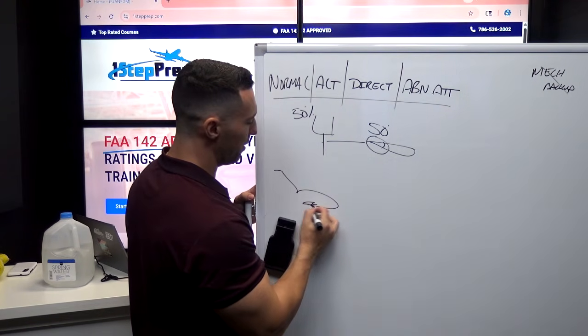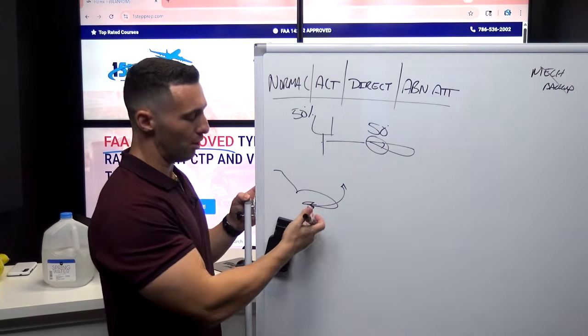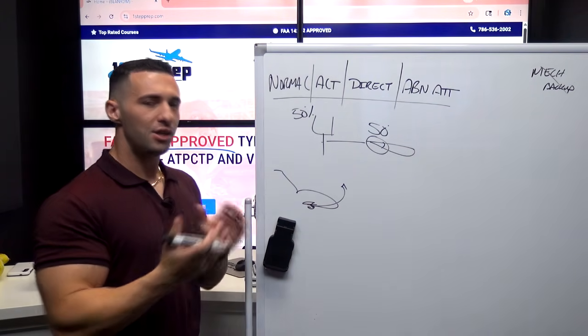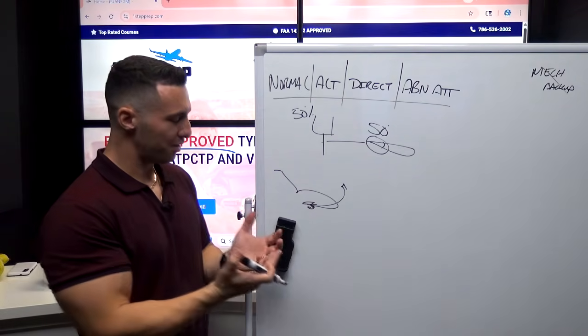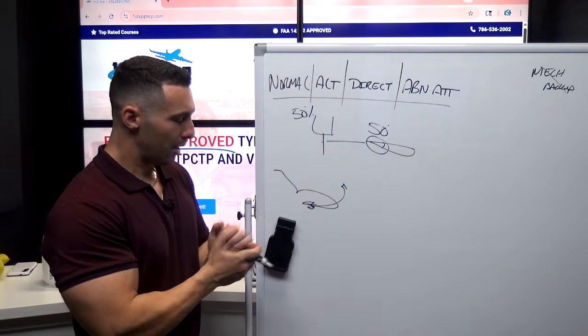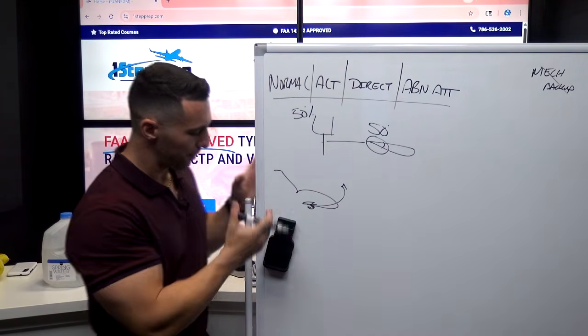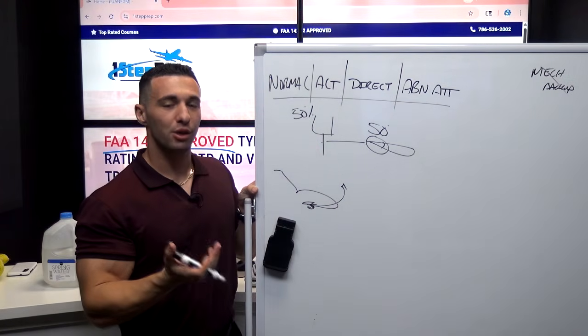You would expect a very dramatic nose up pitching tendency because ultimately the engines are mounted under the wing, and any jet, this is a universal aerodynamic principle, when I apply thrust to an underwing engine mounted aircraft, then effectively that nose up tendency is going to be pretty aggressive.